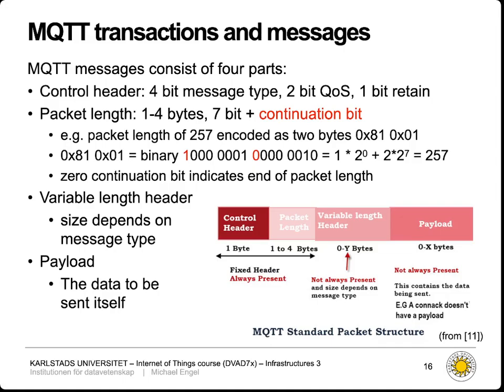And then we add it with the least significant byte first. So the first 7 bits indicate the least significant 7 bits of the length. If the most significant bit, bit 8, is 0, then that's all. So we can have messages from 0 to 127 bytes of length.